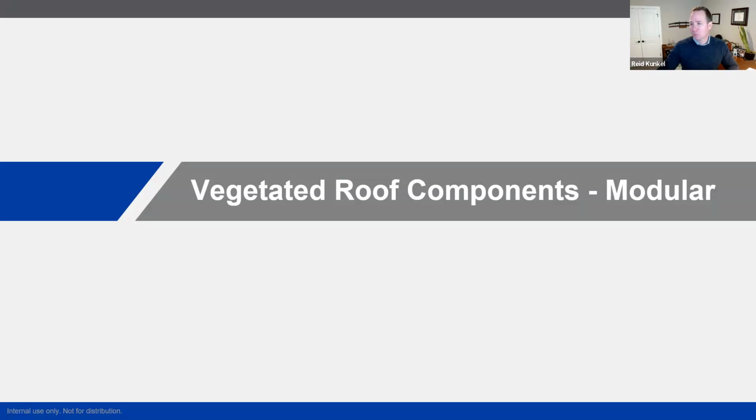And then, when would IRMA roofs be used versus standard roofing applications? Again, that kind of goes back to a substrate and type of construction question. So we see IRMAs, I think, most commonly in commercial construction with concrete decks. We see that more centralized in major urban areas, whereas when we get to less dense areas, maybe more metal deck, coverboard type of work, but it just depends on the project, really.